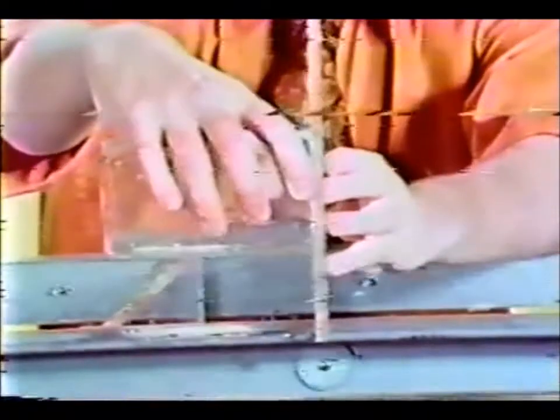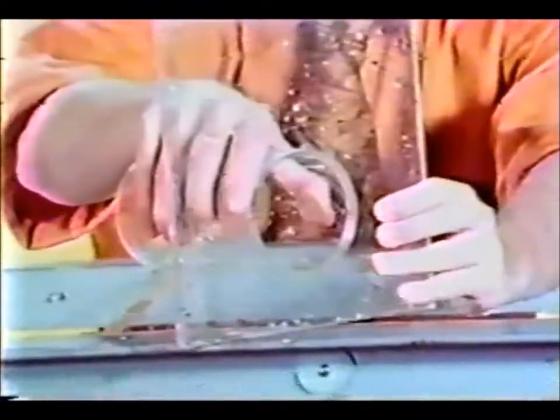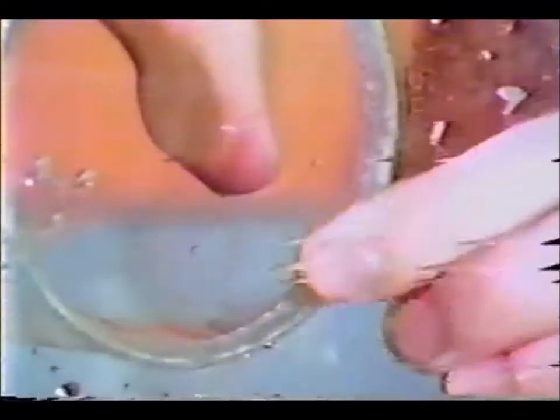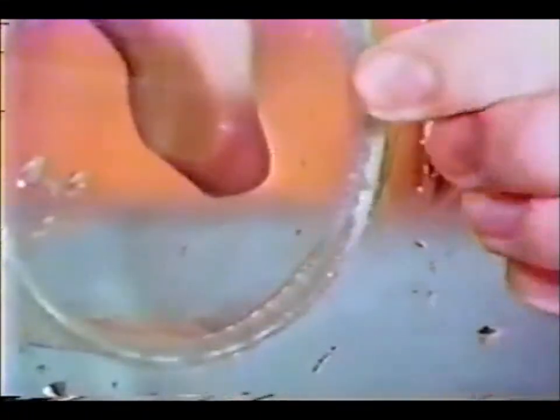This same amount of improvement can be accomplished for a metal pipe by using a bevel. Bevels do not have to be very large. For this 3-inch diameter culvert, the bevel is about 1/8 of an inch. Let's see how it performs. The headwater level is about the same as for the bell end concrete pipe.